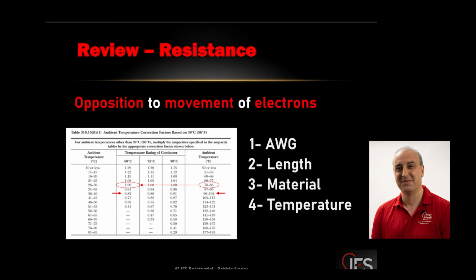So stop me if you have any questions. Normally when I don't see any questions, you're either grasping everything that we talk about or nothing. So I hope it's the former rather than the latter. But we've got to worry about temperature. That was the last item on our 4-item list. So the gauge of the wire, cross section, determines resistance and ampacity. Length of the wire is an important factor. Material, copper versus aluminum, and temperature.